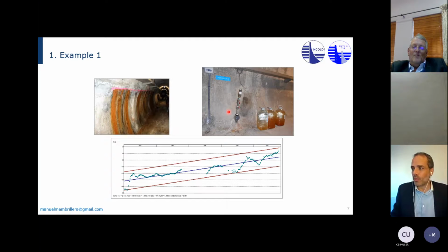And look at the water. So when we opened these piezometers, just look at the amount of material from the foundation. By the way, the foundation is really sandstone and marl, pseudo-horizontal sedimentary rocks, and with gypsum as well. And just look at the gallery as well. This seepage in the gallery, because of the pressure and how the material is really dragging silt from the core. So if you analyze this material, it is actually the core and the foundation.